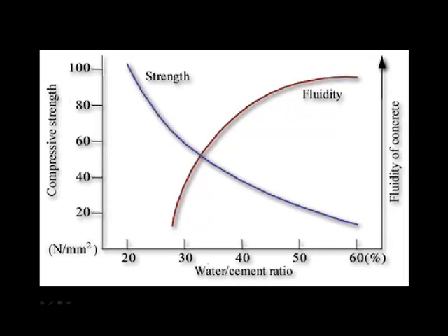Now, of course, if you overdo it, you really should reject that concrete truck and send it away. But in the real world, this rarely happens. You need to begin by carefully controlling the amount of water that goes in. Now, you really don't have to carry around in your head the ratios 1 to 2 to 3.5 and how much water. This is all figured out in advance in a laboratory.